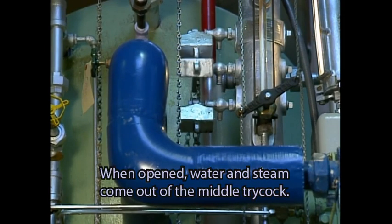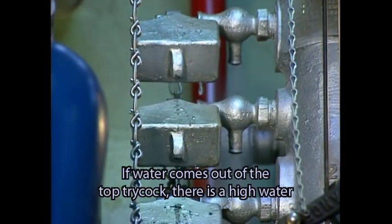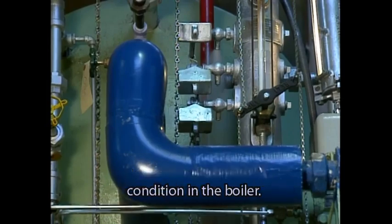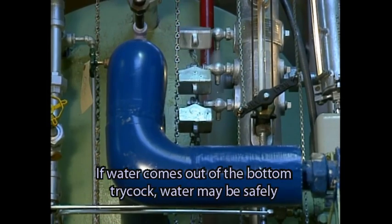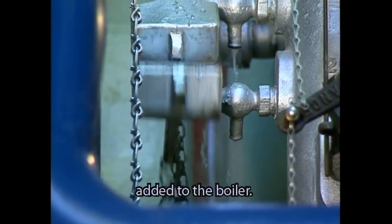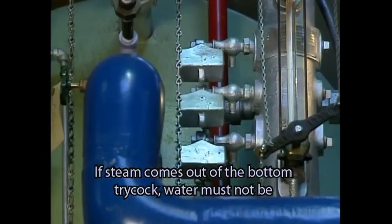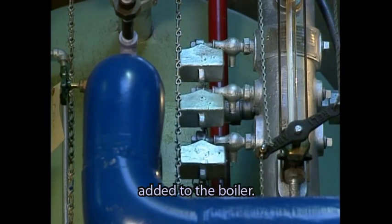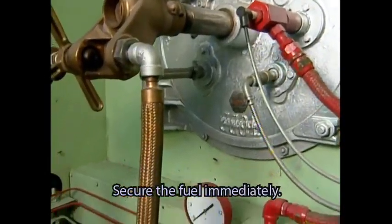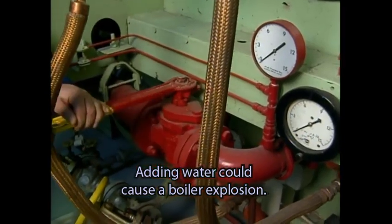When opened, water and steam come out of the middle tricock. If water comes out of the top tricock, there is a high water condition in the boiler. If water comes out of the bottom tricock, water may be safely added to the boiler. If steam comes out of the bottom tricock, water must not be added to the boiler. Secure the fuel immediately. Adding water could cause a boiler explosion.